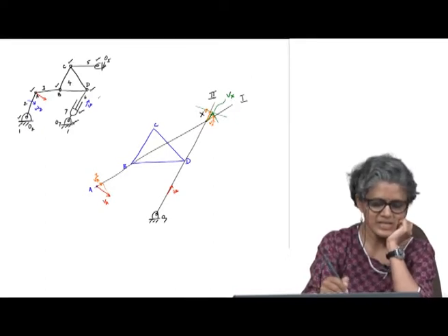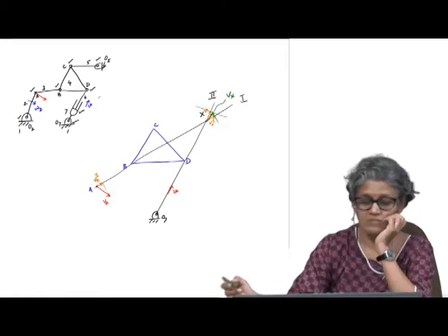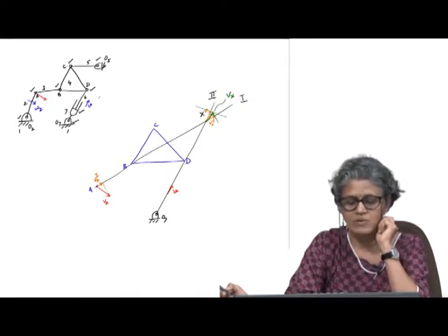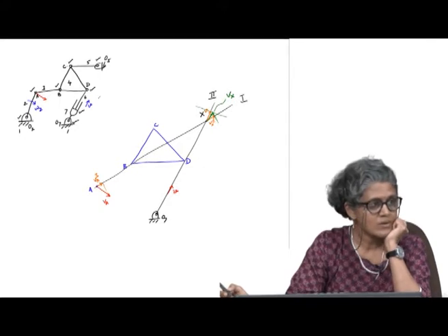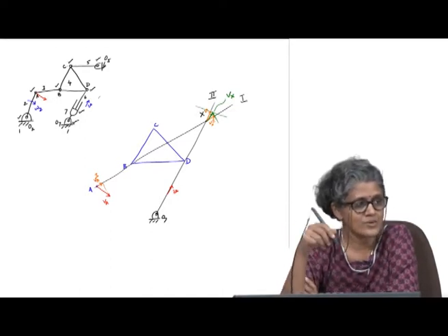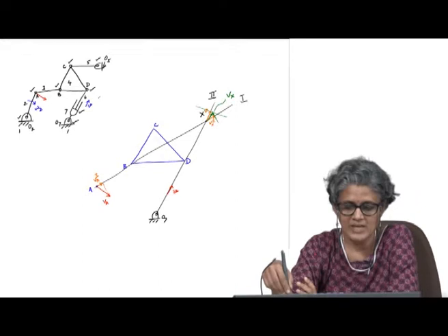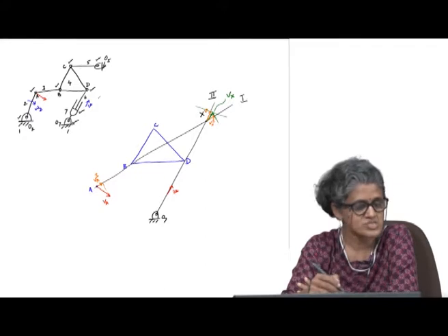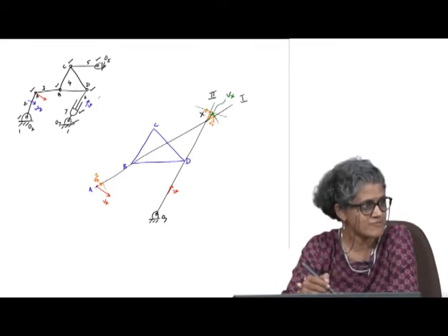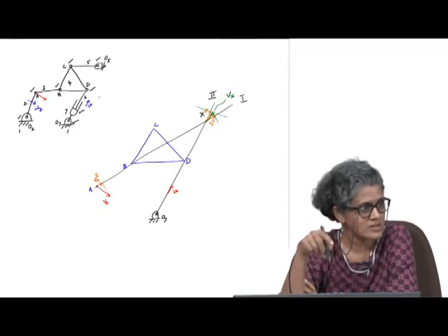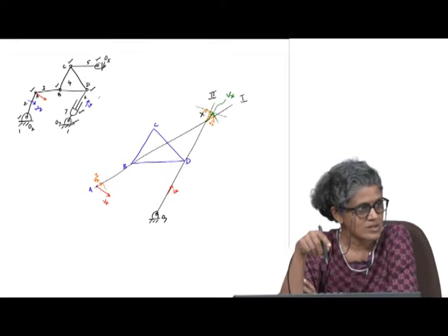This is necessarily the O5x, and O5. So x I know the velocity, but this is not purely rotating about O5. So, I cannot consider O5 and x to be on the same link.